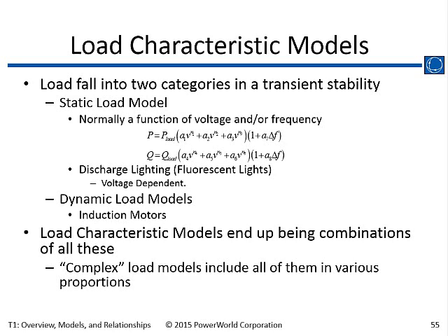Yeah, the question is, I guess you're getting at why don't we have AGC modeled in the transient stability? Transient stability started out looking at how does the system respond to a fault, so how does it respond within seconds after a fault? And gradually it has gotten into longer-term studies where you might say, okay, I have a generator go offline, like in the West, it's a double Palo Verde fault, and maybe I run out 30 seconds and my generation returns to a steady state value, but it's not 60 hertz.